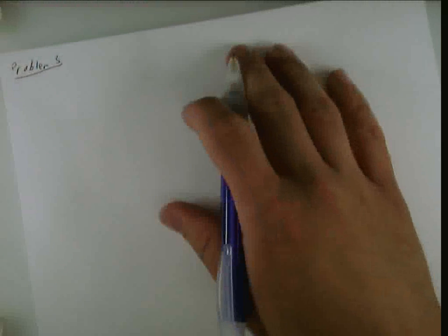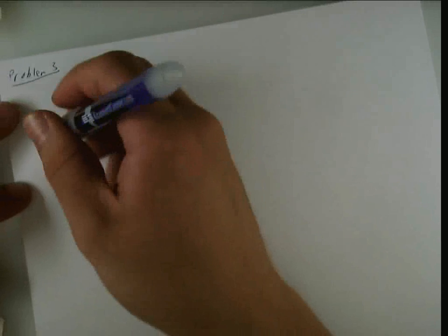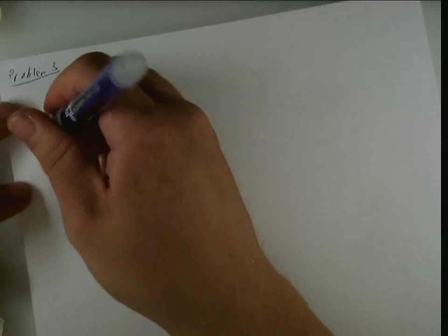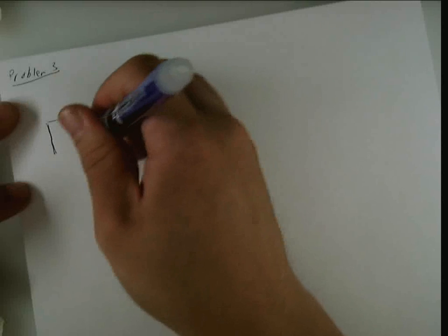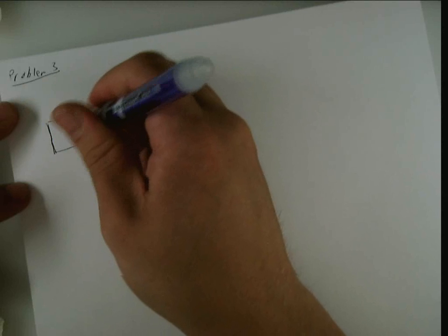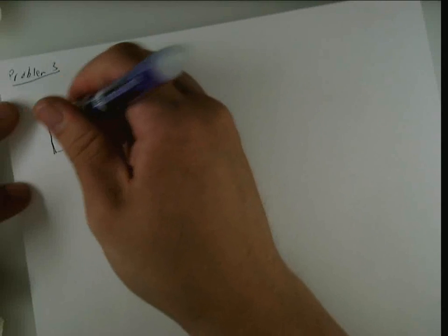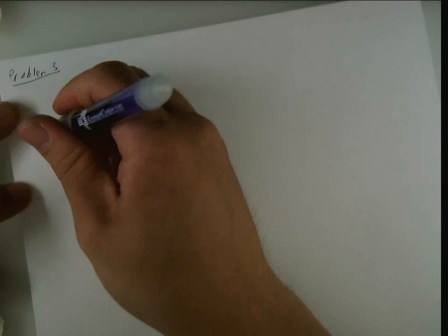And let's get going then. As I said, I'm going to want to use D flip-flops as well as a mux in front of each input. Actually, I'm going to make this my mux. So this is a 4-to-1 mux with inputs 0, 1, 2, 3, and S1, S0.